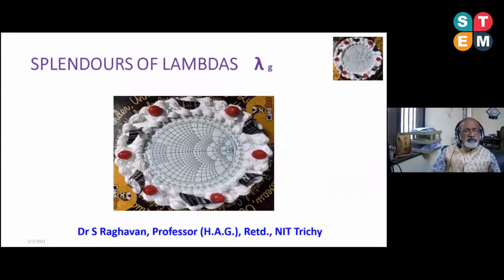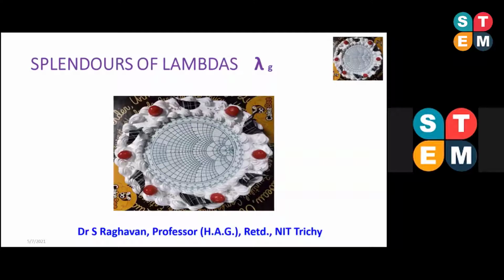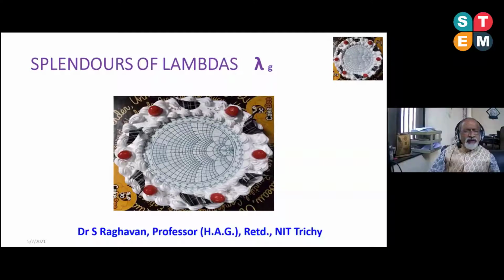See, everything is in lambda. See, waveguides are there. In certain cases, waveguide also will not be used. You should go for integrated circuits, and at microwaves they are called microwave integrated circuits. And the backbone of the microwave integrated circuits are well known: strip technology, microstrip, slot line, coplanar waveguide, coplanar strip, fin line, like that. In any case, the only mantra is miniaturization.